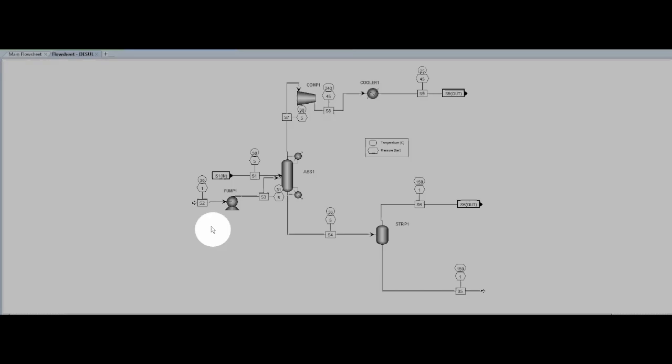Desulfurization. This step is vital as hydrogen sulfide can poison catalysts used in the process. Starting from the absorption column, the feedstock introduction of an amine solution completely removes all hydrogen sulfide in the stream. The sweetened feedstock then leaves the top of the column to the NGL recovery section. The bottom stream then enters a stripper column, which allows for the recycled makeup of MDEA.